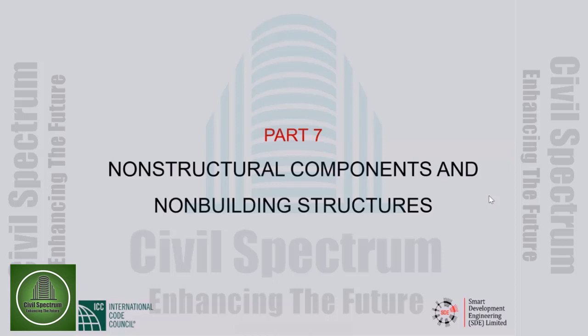The real answer is that unless you have a very unsymmetrical building, gravity loads do not cause significant lateral deflection. So the drift that we are talking about is caused by the earthquake forces or wind forces.